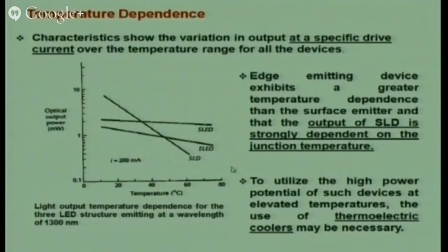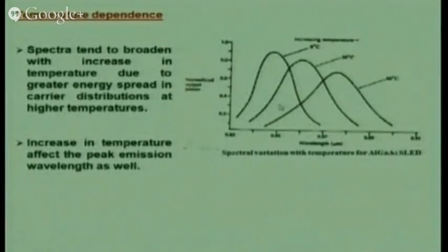That means while making a laser driver or LED driver, I must look for temperature compensation also. That means I must look for a heat sensing device within that system and control the setup itself. So I must look for thermoelectric coolers. We'll discuss the electronic circuit of that later on.